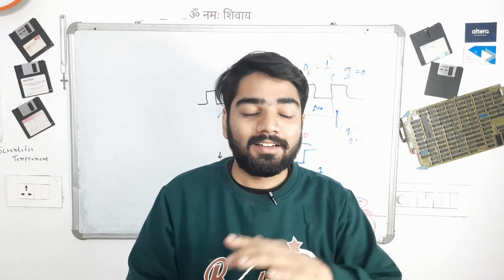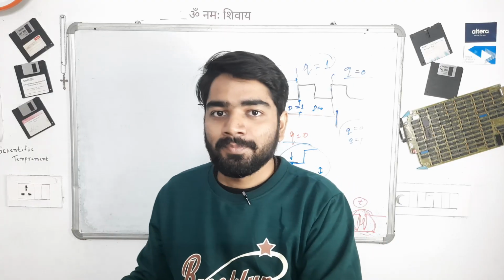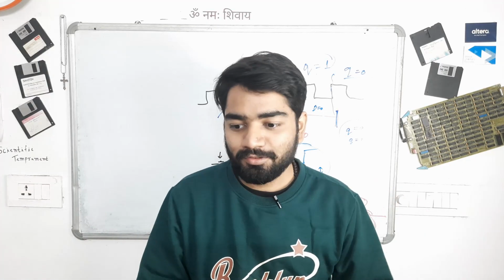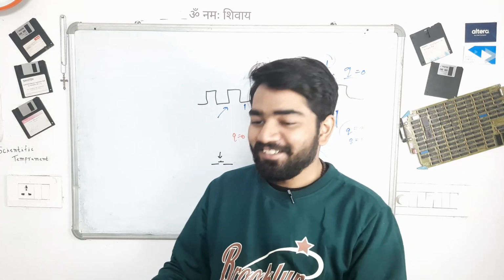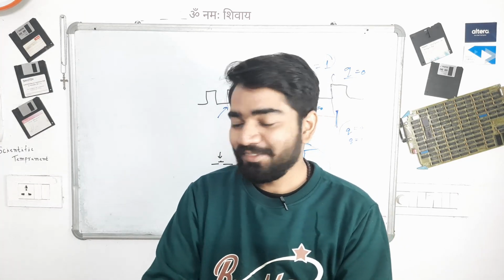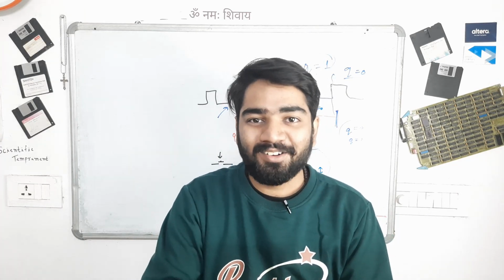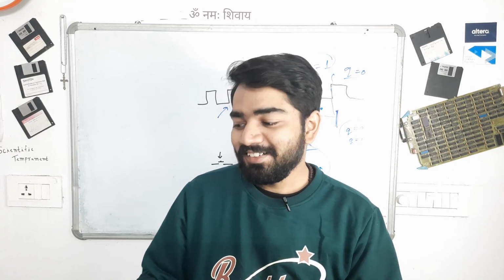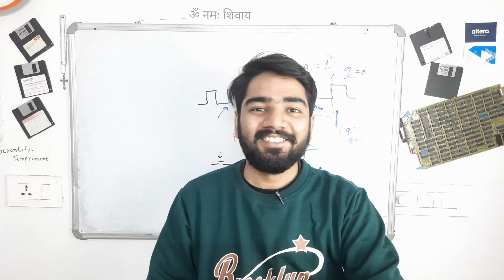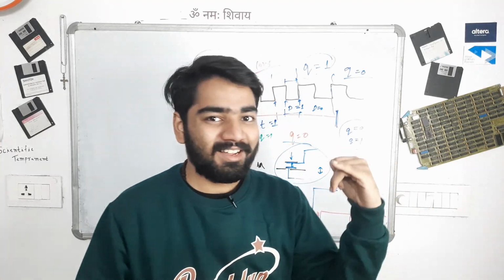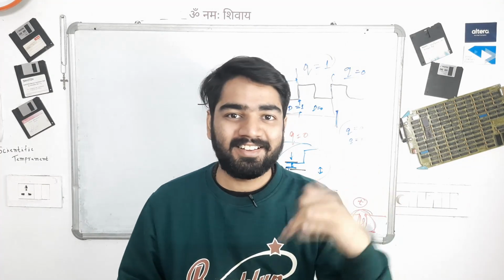So that we will see again in the clock division video. I'll show you this again and I'll show you the proper functioning. Many beginners get confused when these kinds of things happen, when they put a very high speed clock pin directly into their design on the FPGA, and they see these kinds of effects. They get confused about what is happening. So this is what is happening, okay, and we will fix this as well.